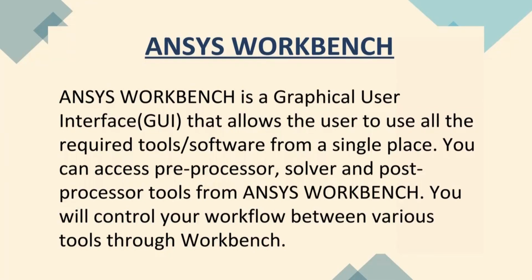And after that, if you want to do the post processing using CFD Post, then click CFD Post. It can take all the results from the Fluent you already calculated. So it's a fantastic way of working using Workbench. You don't need to do all these components separately, because geometry is separate, meshing is separate, and then you set up and then you run. All are actually separate files. But the Ansys Workbench is connecting everything together. So it's a very nice tool.